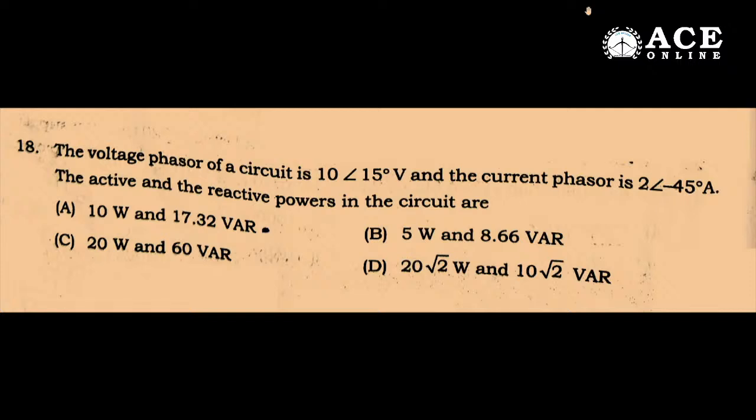The question is, the voltage phasor of a circuit is 10 at an angle 15 degrees volts and the current phasor is 2 at an angle minus 45 degrees amperes. Find the active and reactive power. Guys, you are aware that whenever the applied voltage and the resultant current are given, if you want to get the resultant power, or the active and reactive power combination, it is nothing but the complex power, S is equal to...